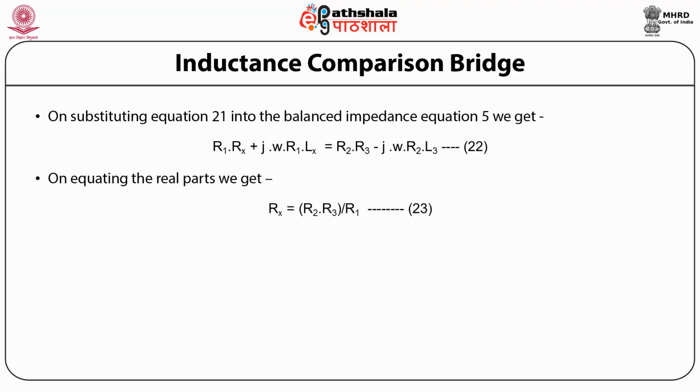On equating the real parts, we get Rx = R2·R3/R1. This is equation 23. On equating the imaginary parts, we get Lx = R2·L3/R1.